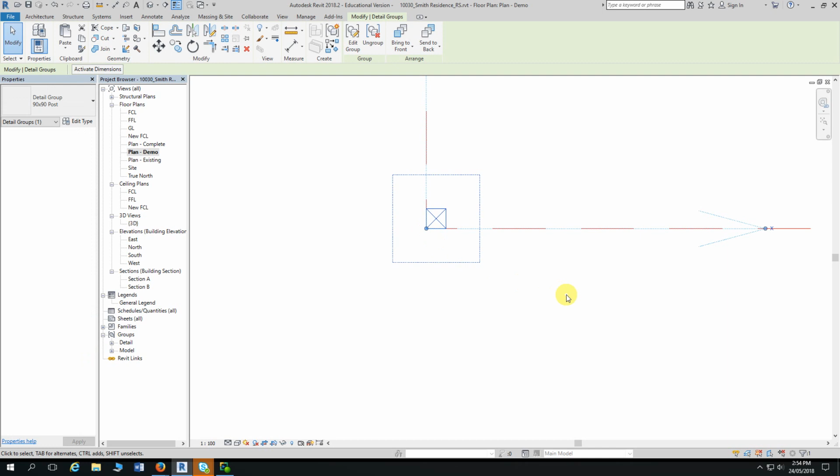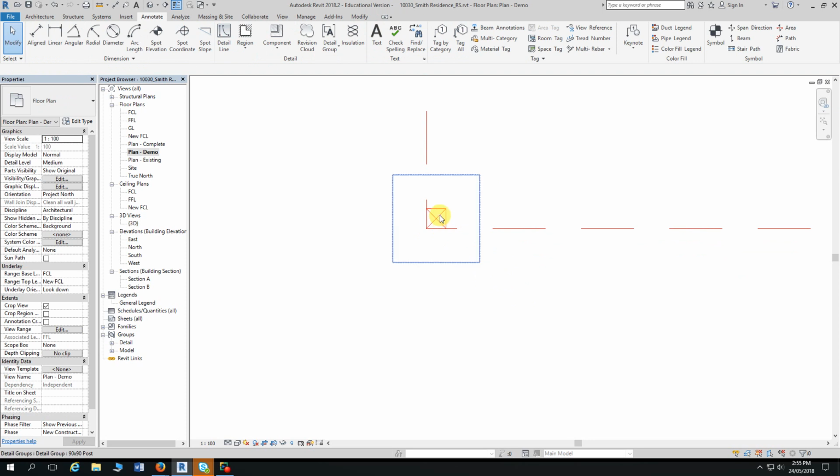Do you remember that you used a group origin when you placed the roof and the floor? That's how I established the origin point for the model groups. So you can move that and place it somewhere appropriate because when you're copying this group or adding more of these, you then get a usable base point or origin for placement.